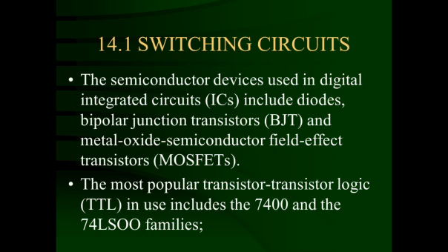So nowadays, out of the five types of TTL I told you about, the standard TTL 7400 is used to drive a higher current capacity. That means to drive a relay etc., you need higher current, you need a higher fan out. For that, the standard TTL 7400 series is utilized, and conventionally 74LS, that is the low power Schottky TTL series, is utilized.